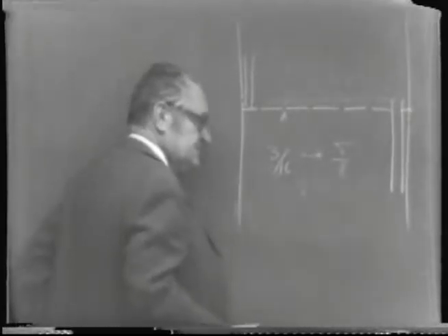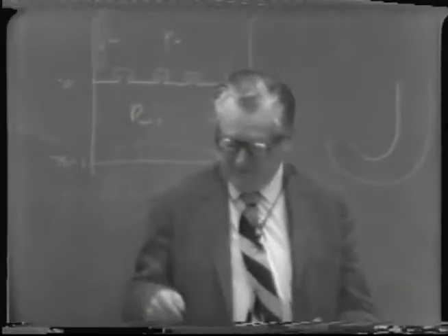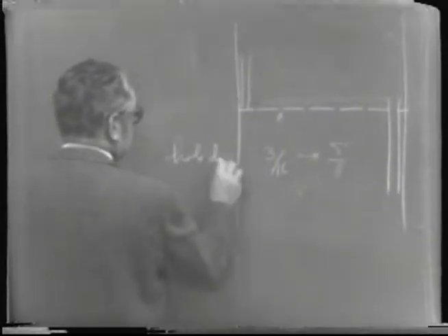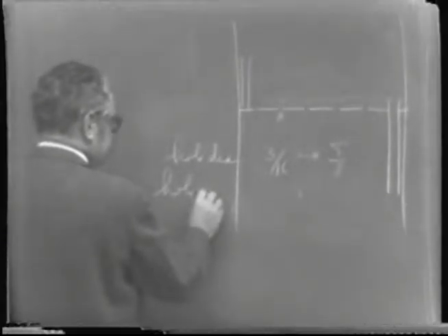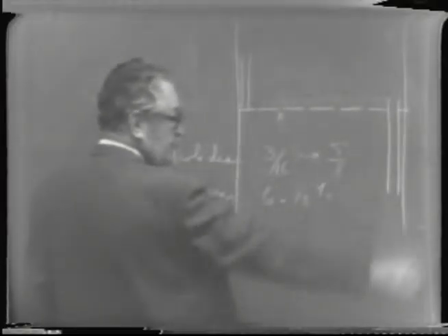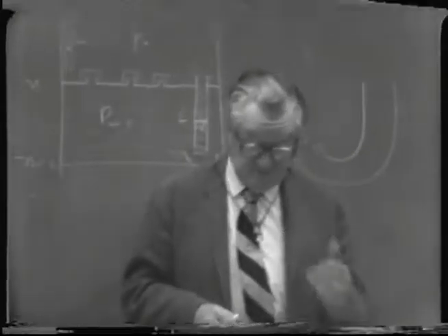That'd be about the largest that would be recommended for the alcohol industries. That's the figures I remember. Those would be the hole diameters. And the perforated area would be somewhere between 6 and 10% of the overall plate area. 6%, I think, is more common, by at least one of the manufacturers in California.